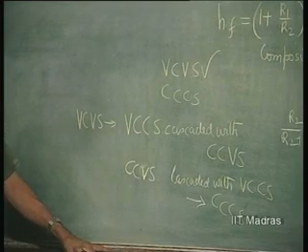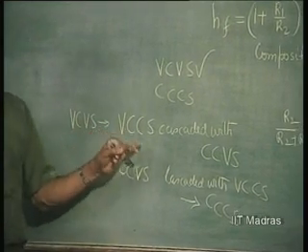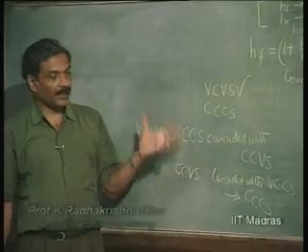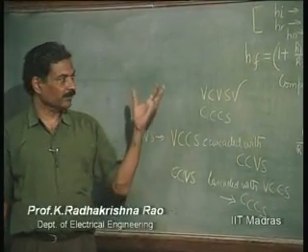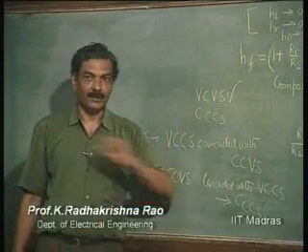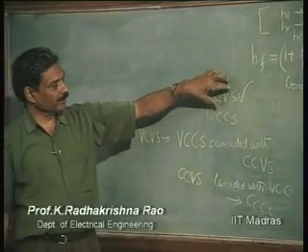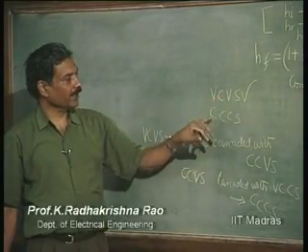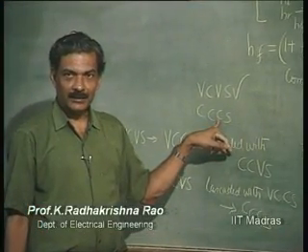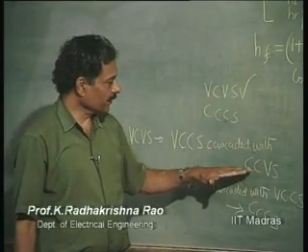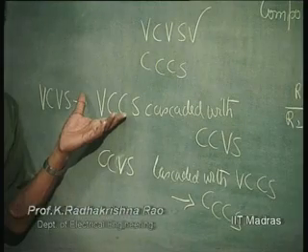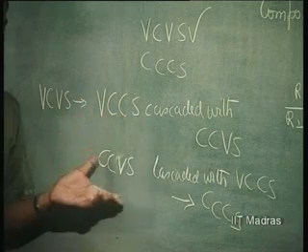So, if you are able to develop good voltage controlled current source and good current controlled voltage source, that is sufficient. You can realize all the idealized sources, that is voltage controlled voltage source, current controlled current source, current controlled voltage source, voltage controlled current source. Whereas, if you realize good voltage controlled voltage source and current controlled current source, you cannot realize the other two sources by simple cascading. So, current controlled voltage source and voltage controlled current source are basic sources. If you realize these, then by cascading we can realize the others.